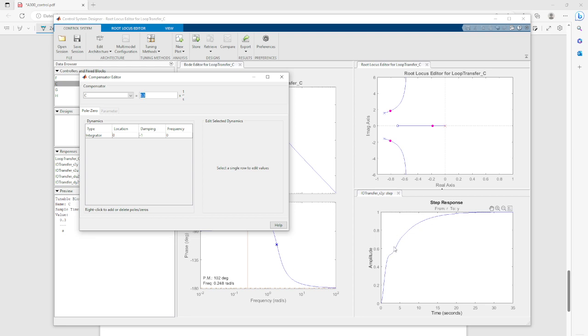But we have a little bit of this strange behavior. Why don't we have the overshoot? Because we have a pole now here at minus 0.2. This very slow pole dominates our response, and this is what you see here. We are at a time scale of 25 seconds. This is definitely too slow for an aircraft.